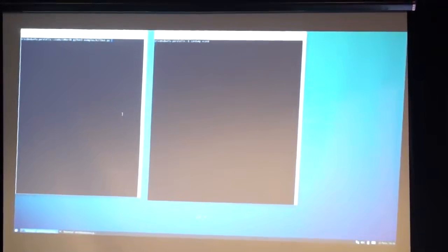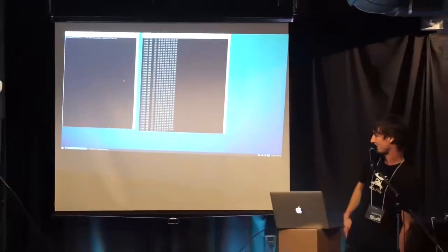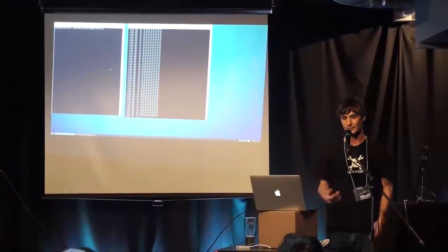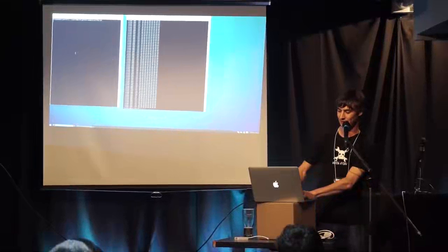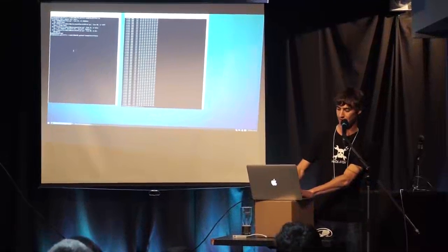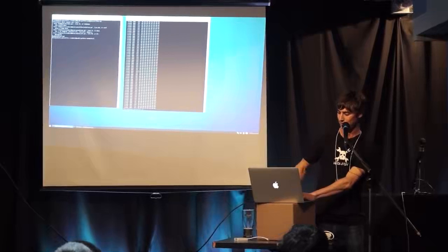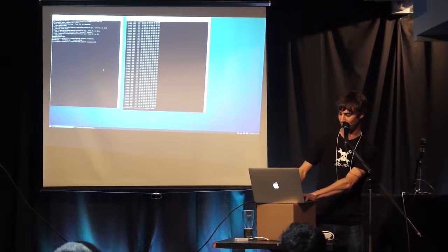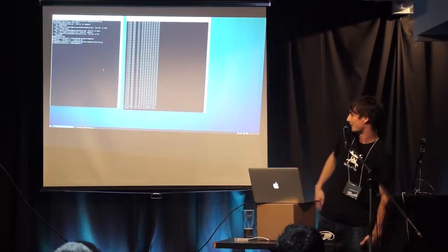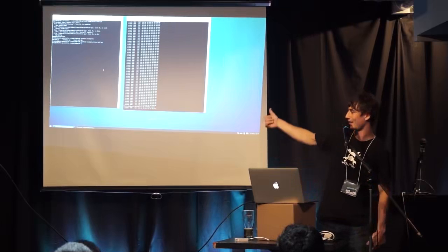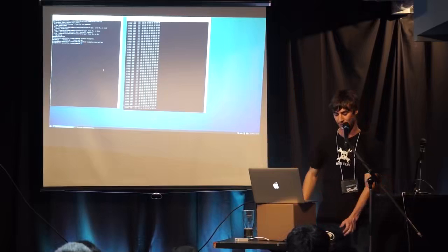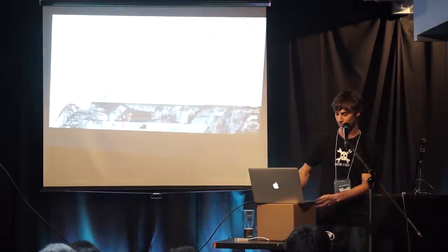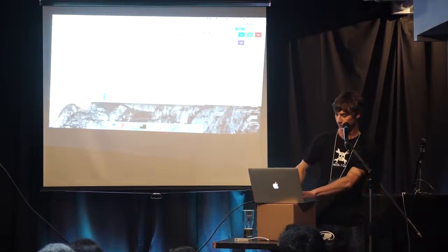And I'm going to run my kill the bus example, and it's not going to be very exciting other than it's going to spam messages. But of course, if I were to hook that up to this Peak device instead, it would be sending real CAN data. And then the other simple example that I've written, the code that I showed you there, is this clear the MIL. You might not be able to read it on the right, but what did I call that? Reset mil. Bam. So it's just sending the one message on the right. It's really super pixely, but that's the candump utility, which is kind of neat. You get on a CAN bus, you run candump on your computer, and you'll actually see all the data in a loggable format.